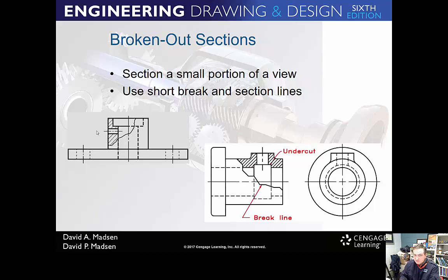See, you need to remember datum planes. Where am I dimensioning from? You need to think about that and dimension from the same ones on each view. If you're going to dimension from the bottom and the left side and the front, then those are the planes that you need to dimension from in each of your views. So in this case, let's say I was going from the bottom, I'd have a dimension from here up to the center of that, located on this side over here, and then I would have a note with a leader showing, hey, this is how big it is.